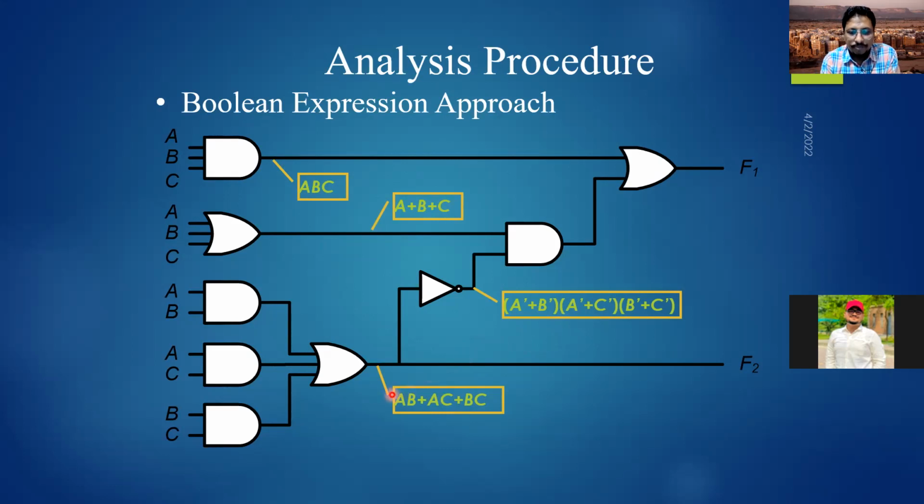Just when you take the inversion, or the complement value, of this, what you will do is invert it all, you will put a prime on it, then you will change it. Each multiplication, you will change to plus, and each plus, you will change to a multiplication. It is basically not multiplication and plus, it is ANDing and ORing gates. So these two functions here have an AND function. After inversion, they became complements first, and second, they will become an OR gate.